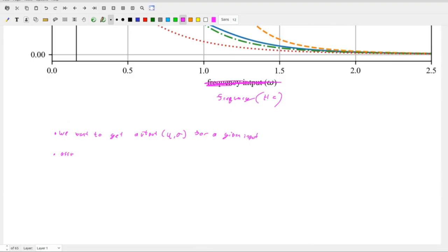So assuming the expected value of x is equal to 0, the mean square of a power spectrum density is the expected value of x squared, which I think we also called x squared with a bar over all of that, is equal to the integral from negative infinity to infinity of |H(jω)| squared times the forcing spectrum S(ω) with respect to ω.